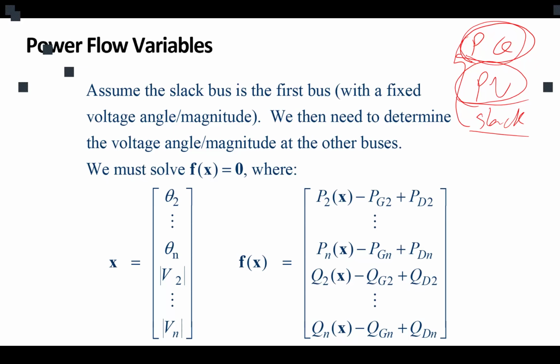When it asks for per unit in the load, do I use the reference, 1, or do I use the deviation I want from 1? Deviation, because that should change. Other than a slack bus, all the voltages should change. Are we good?